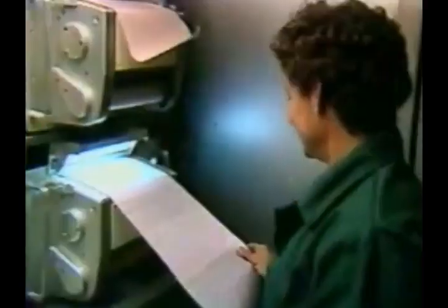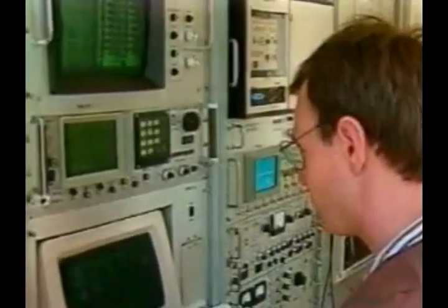As shown here, rigging up includes laying out the logging tools, testing the cable head and cable, testing the logging tools, checking out the surface equipment, and making routine checks of mud properties. As logging devices are assembled together and the string of tools is made fully operational, a before-survey calibration check is made.